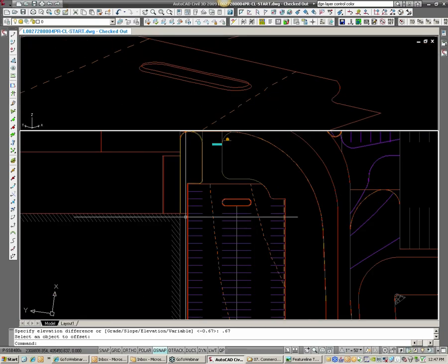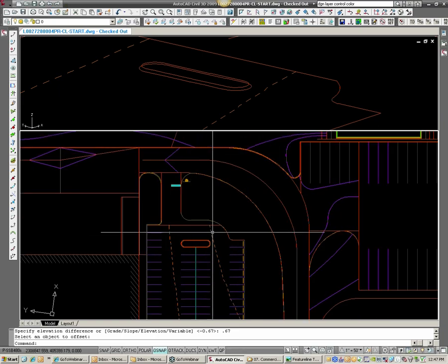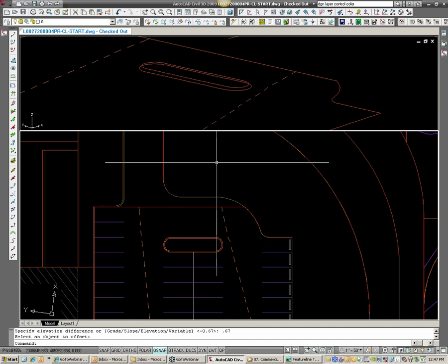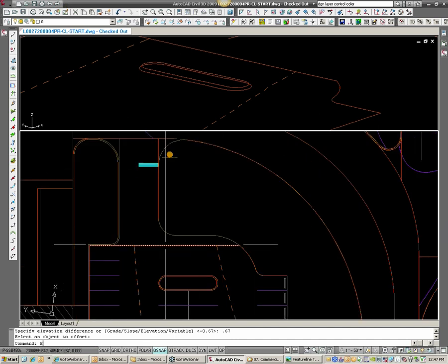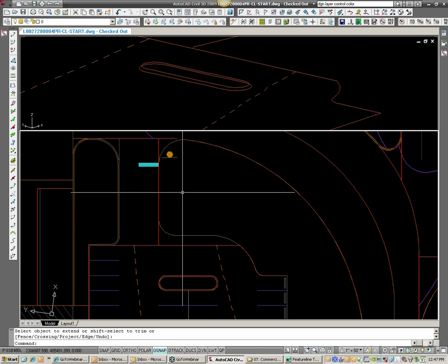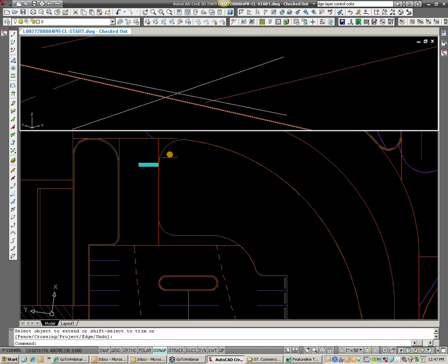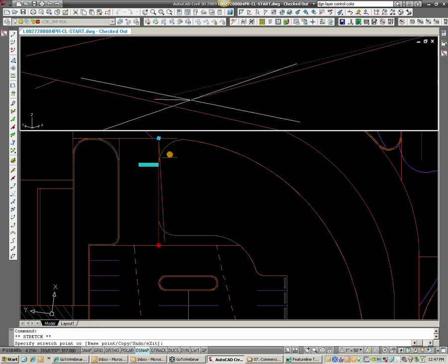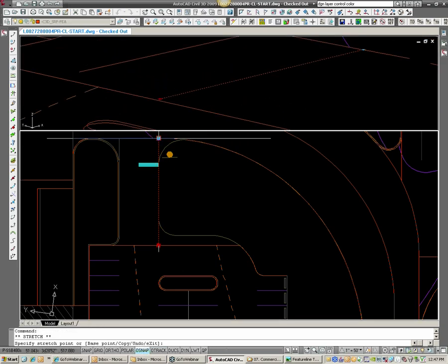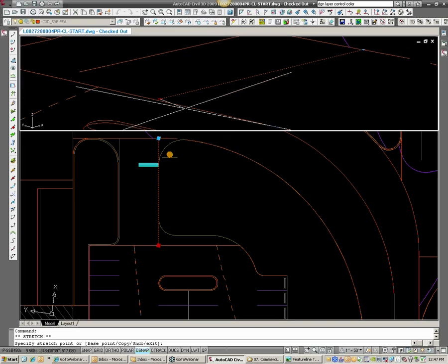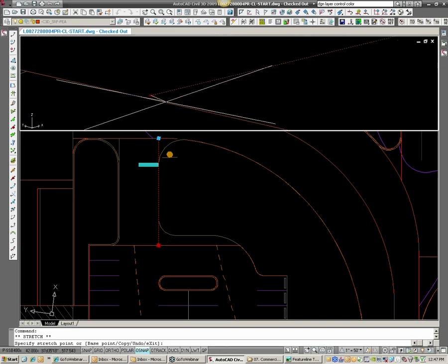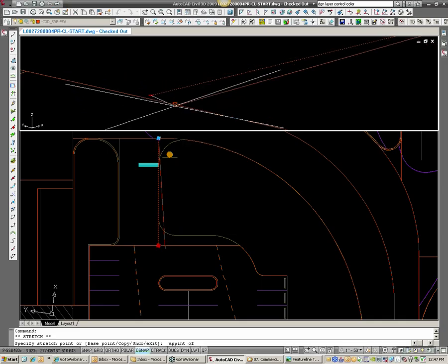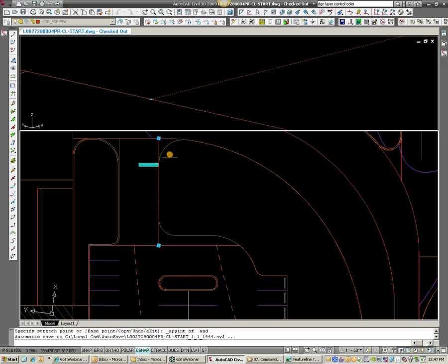So hopefully through this simple exercise, essentially that's commercial grading with the tool. You're drawing feature lines, drawing them out, drawing them here and there. What I would do in this situation is I extend this feature line up to here. You can see that there's a difference here, that I already had drawn in. So I can either snap this road feature line down to the driveway or bring the driveway up. Looks like ultimately I brought the driveway up, but in this situation, let's just snap this back down. So let's take that, snap it back down.